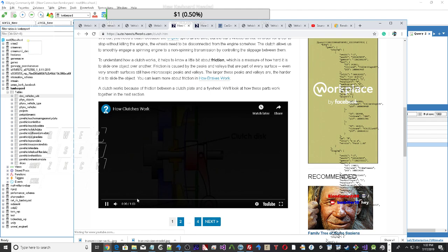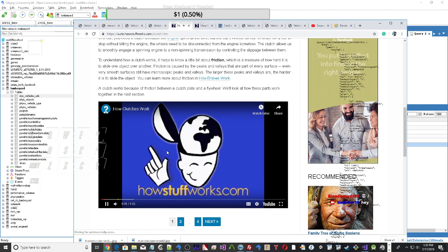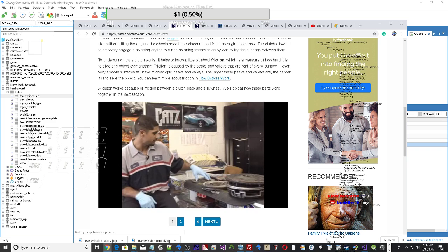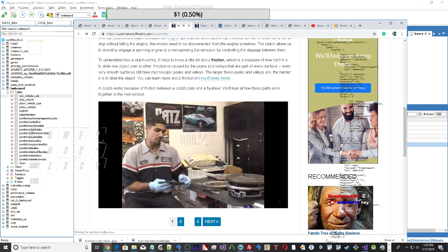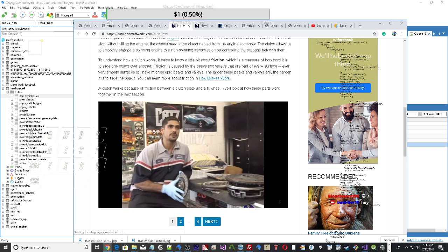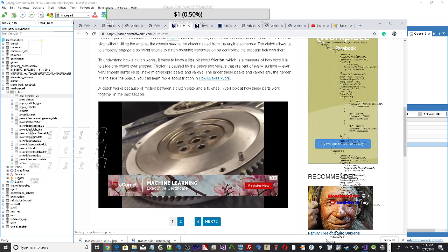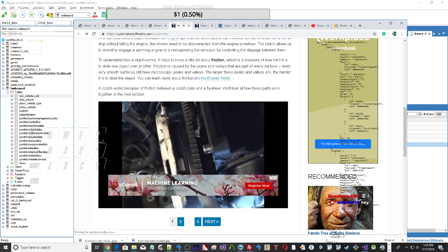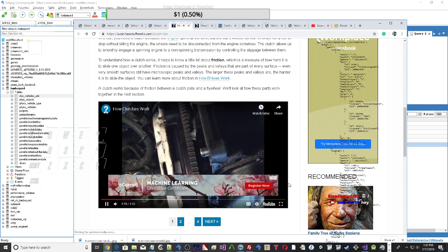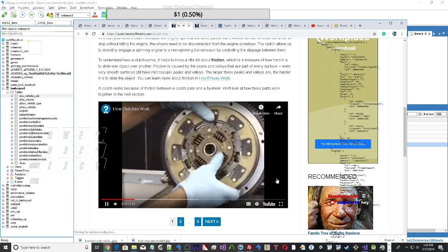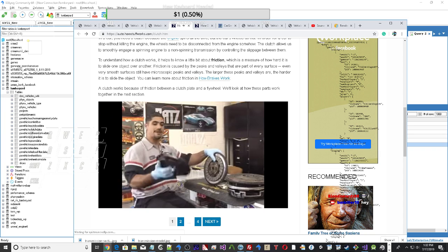wheels[PxVehicleDrive4WWheelOrder::eREAR_LEFT].mMaxHandBrakeTorque = 4000.0f; wheels[PxVehicleDrive4WWheelOrder::eREAR_RIGHT].mMaxHandBrakeTorque = 4000.0f. Enable steering for the front wheels only.